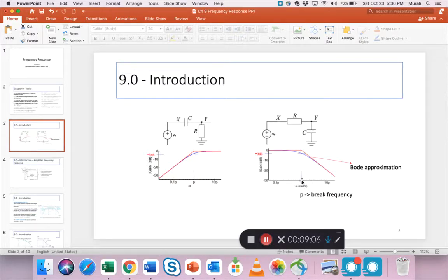So over a travel of a 10 multiplier of the frequency, the decibel value falls by 20. So you can see that it falls to minus 20 if it was 0 here, right? That's why we call the slope of this line 20 decibel per decade slope. In this case, it's falling minus 20 dB per decade. In this case, it's rising plus 20 dB per decade.